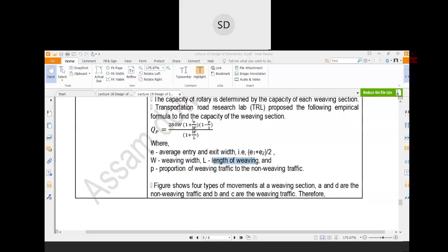After estimating the capacity using this formula, which is basically the theoretical capacity, you can go for a traffic volume study in the intersection. You can find the total traffic volume in the particular intersection area. Suppose for some intersection you find it is 1000 vehicles per hour.